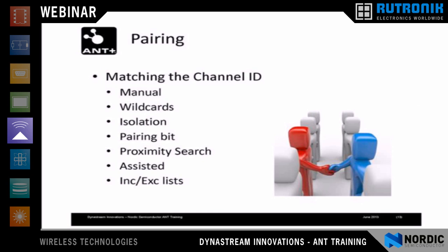You can choose a wildcard, which means that when you're opening up your receive, you look for any of the device IDs, or any of the device types in the neighborhood, or any of those pieces, whether it be the device type, the device ID, or the transmission type. You can lock down with a number that you know already.